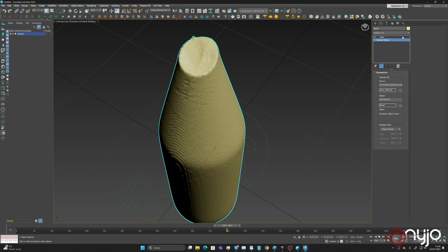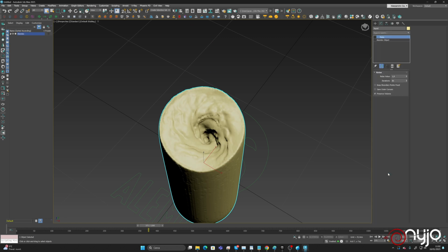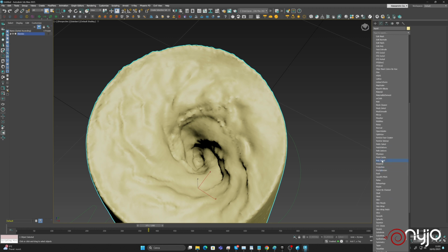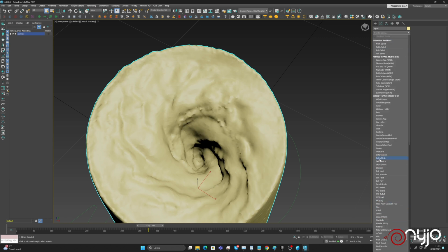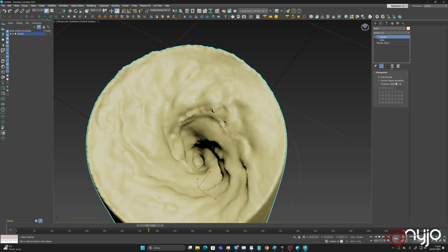I can say that just to be sure, we should create something that is more complex. By the way, let's see if we go with a turbo smooth, it's losing the smooth value. So let's try with open subdivision. Okay, we are losing the same. By the way, let's say that we have a smooth modifier. Obviously, I like to create something that can work easily, let's say 75 for the threshold.